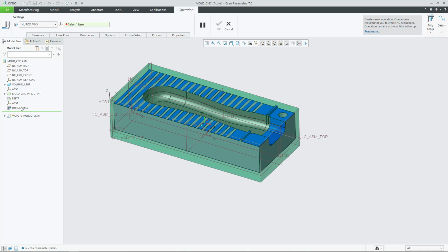So you can see, because we've already created that, it's been accepted, but we can have a list containing multiple machining centers here. So we can write programs from within Creo that are intended to be cut or intended to be run on multiple different machining centers, maybe with different attributes, different horsepower, different maximum RPMs, different extents of travel on the table.